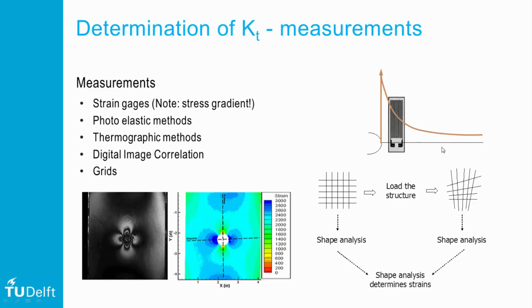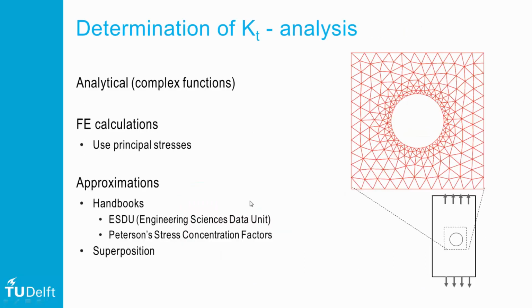If one takes two or three strain gauges, one may approximate the gradient and extrapolate it towards the notch edge to estimate KT. But even with strain field measurements, stress gradient extrapolation towards the edges is required. Similarly, one has to consider that finite element analyses often give stresses which are calculated by interpolation within an element, which means that it does not represent the peak stress at the notch root surface itself. For this reason, accurate stress concentration factor determination requires very fine measures.